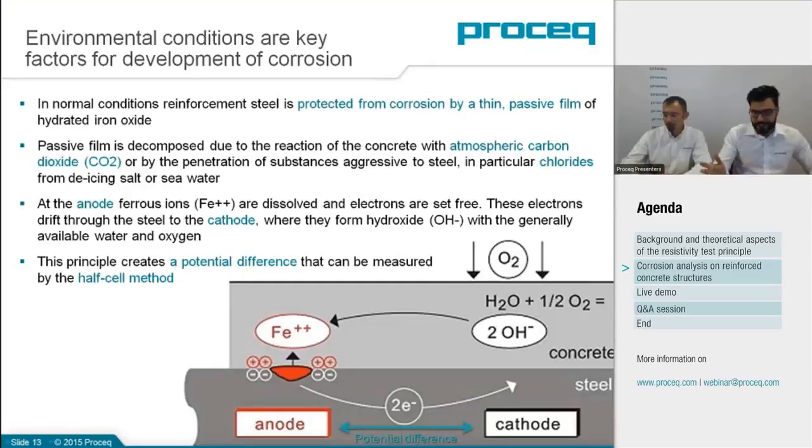Again, the example that Guido has given on the tomatoes and the olive oil, and the protection that's given, applies here. So as you can see, the cement content of the concrete is providing that alkalinity that protects the steel from corroding.